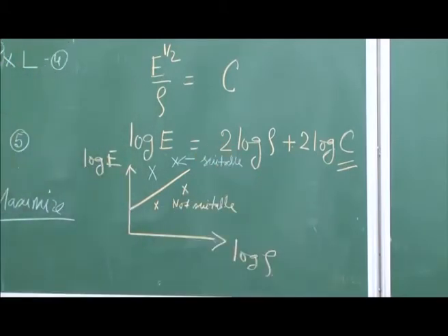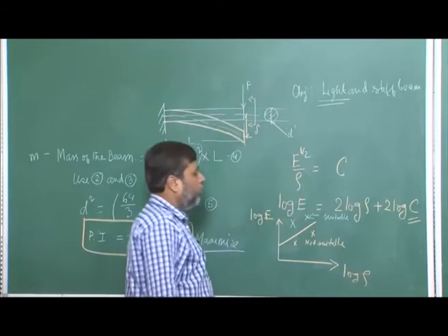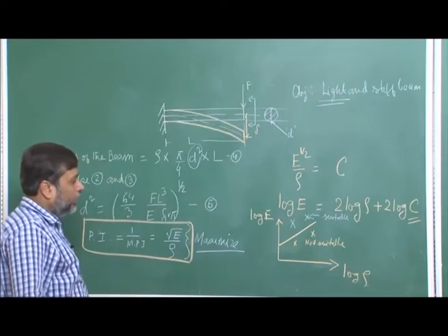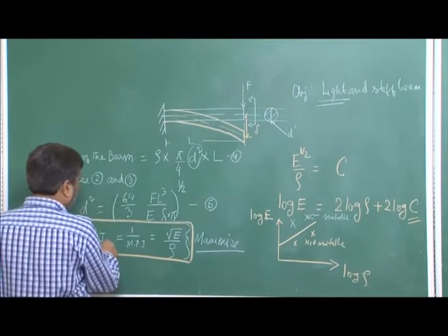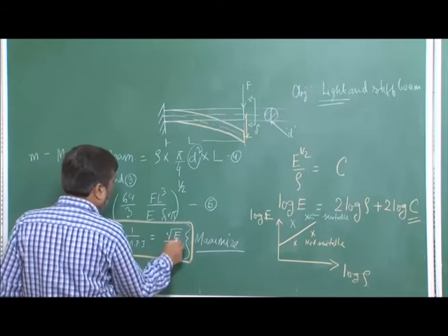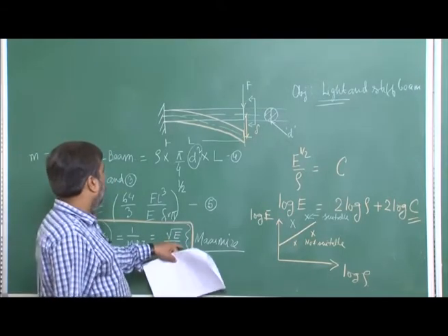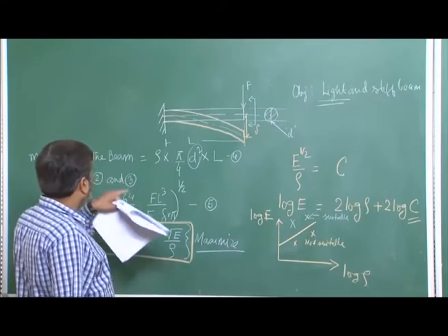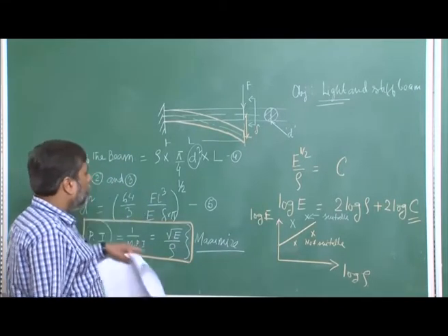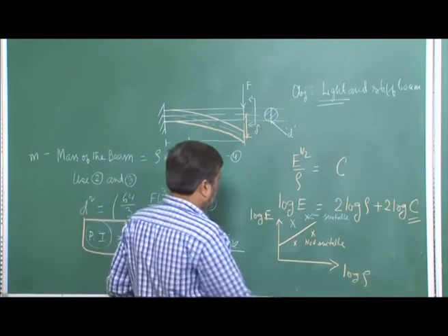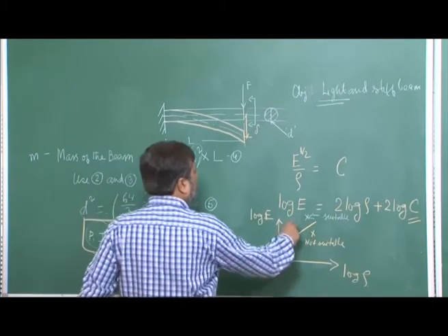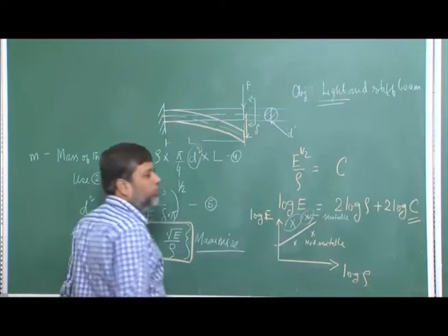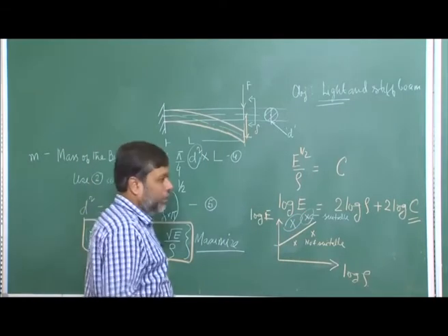So, thus if we have a modulus of elasticity versus rho graph, which is there in the SB chart corresponding to various materials, then on that I am looking for a high value of square root of E by rho, because I know the higher this is, the lighter will be the beam. To do that, if I know my cutoff point, then I can search for materials and find out what will be a very good material for our application.